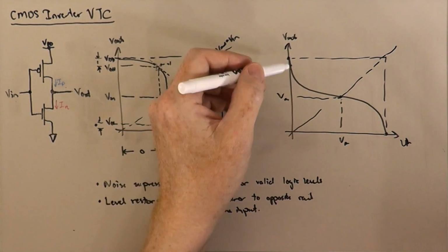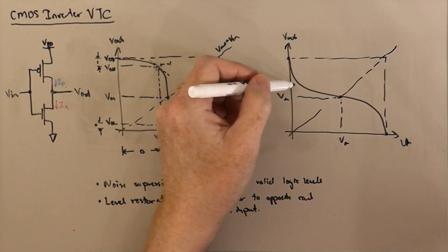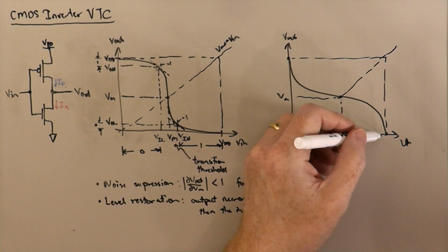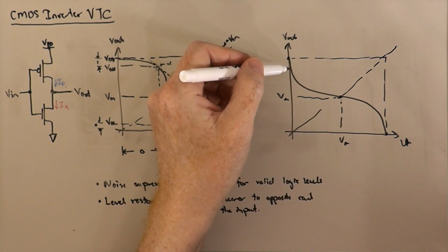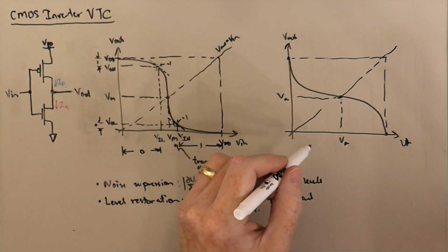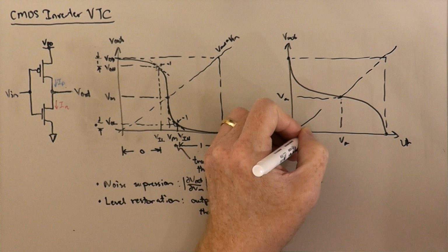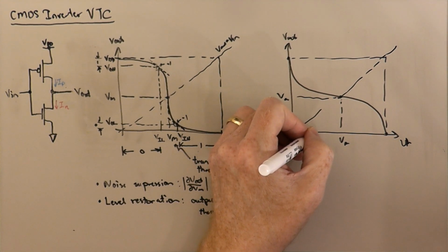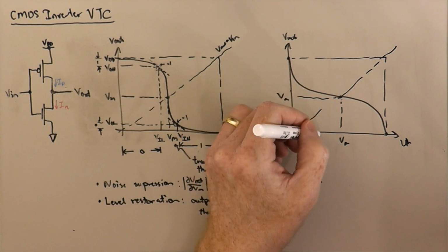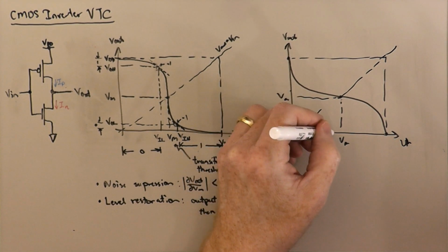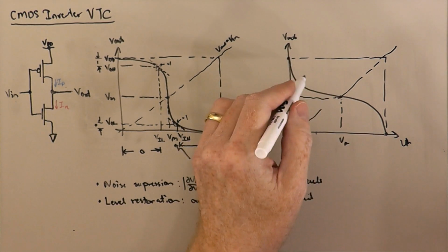So we would get noise enhancement: any little variation in the voltage levels here, in the range that corresponds to 0 and 1, would be amplified at the output, so it would enhance the noise. And if we put in an input signal somewhere in the middle of the rails, the output would get closer to Vm, so we'd be moving the logic levels toward Vm instead of toward the rails.